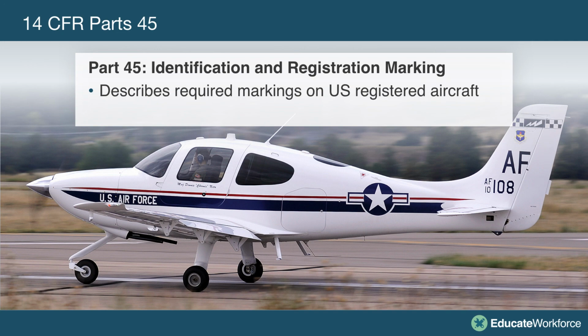For engines, we need to have the established rating, reference to compliance with 14 CFR Part 35, reference and compliance for exemption to 14 CFR Part 34, which is fuel venting and exhaust emissions for turbine-powered aircraft. And then last of all, the catch-all, any other information that the FAA deems appropriate for the specific aircraft is going to fall under Part 45.